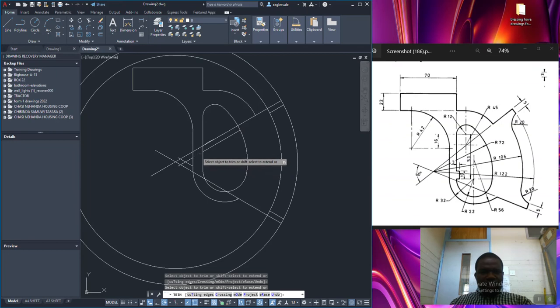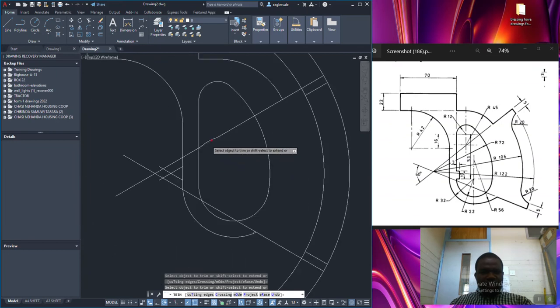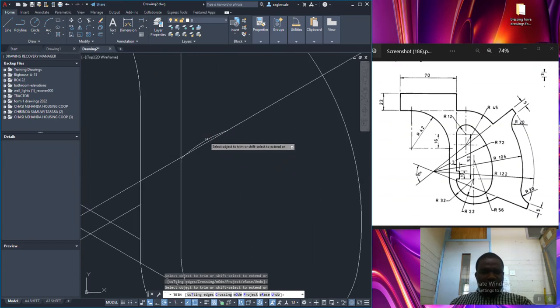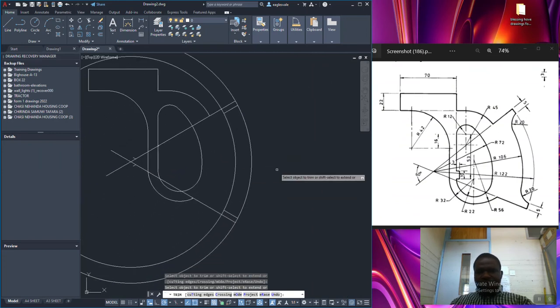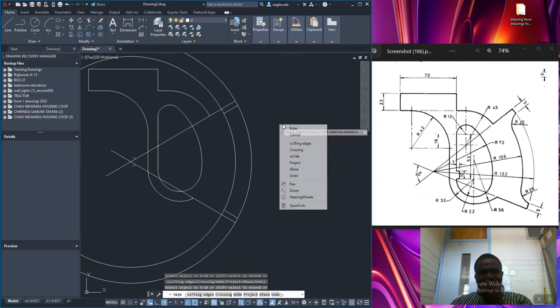We've already located the centers here, and here, and here, and here, and here. I'll finalize them later. So we need to draw this circle here, that is radius 20, and we know that from this is 20, the circle is starting there 20 millimeters, and it's also coming from there 20 millimeters.